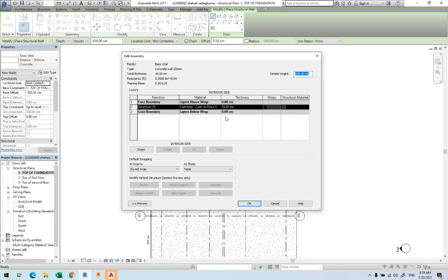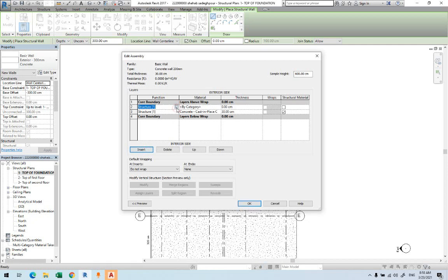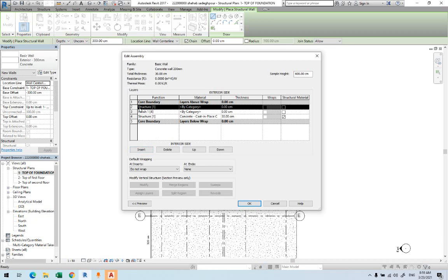But for the structural walls, we don't care about the gypsum things for now. I can add it. For example, I can insert a layer. I can change this one to be a finish or membrane, thermal air layer. So I can do this as finish. I can change the layer. What is the material we have here? Is it cement plastering, gypsum plastering?